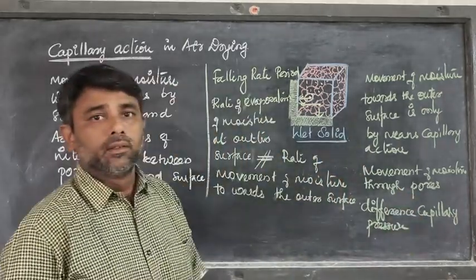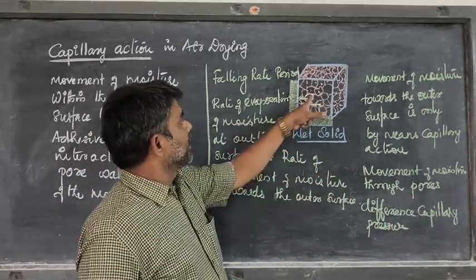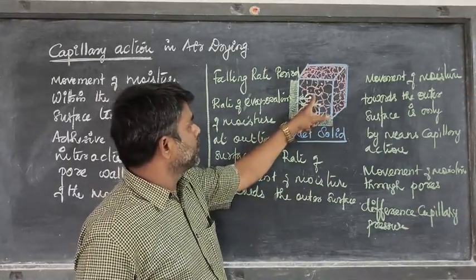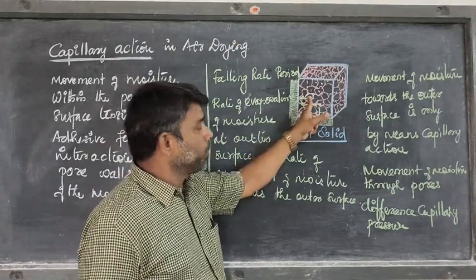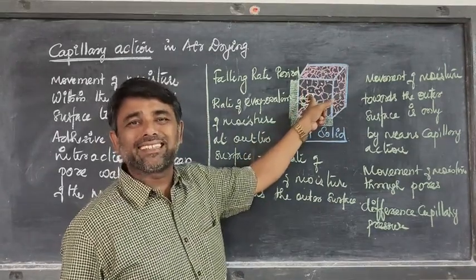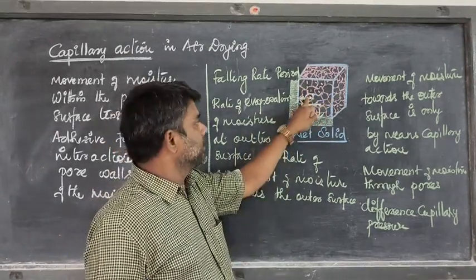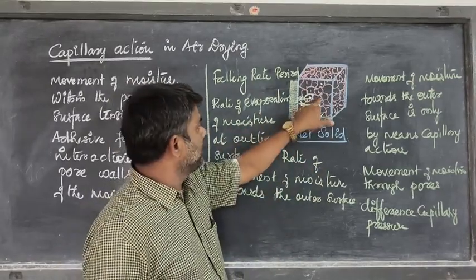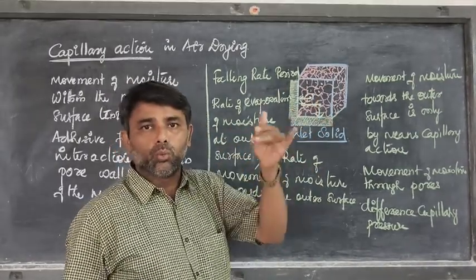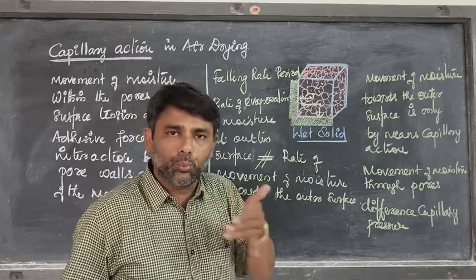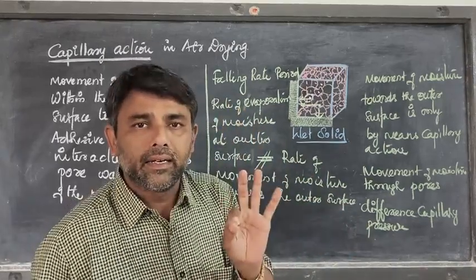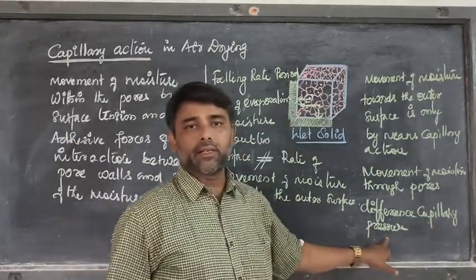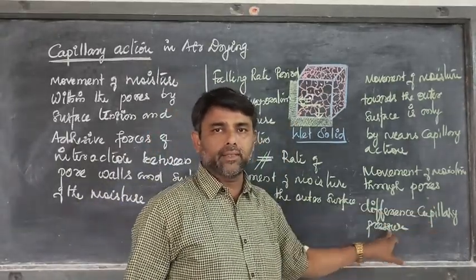Clear? Once the droplets of water move towards the next pore, this pore will be empty. There will be a suction pressure. This suction pressure sucks the moisture from the next pore. So movement of moisture through pores is because of difference in capillary pressure or difference in capillary suction pressure.